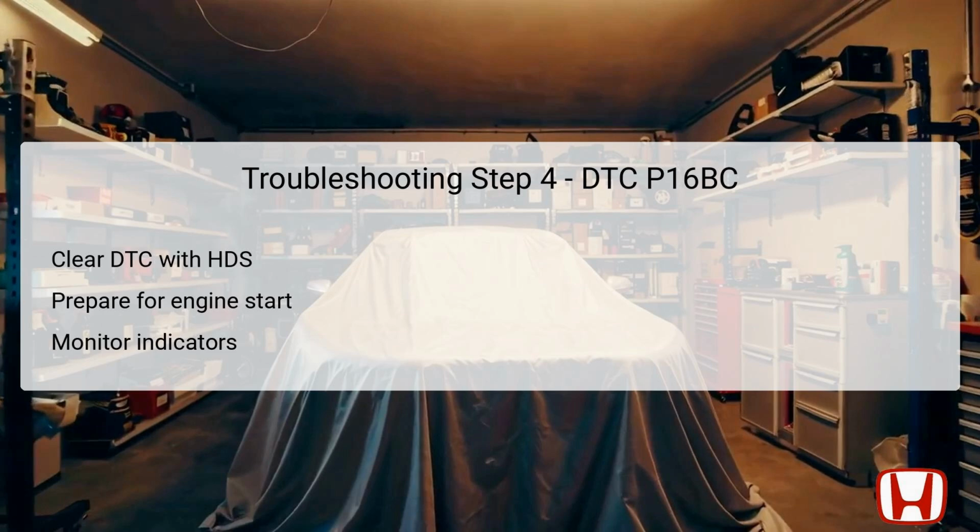After turning the ignition to the ON position, the next step is to clear the DTC using the HDS tool. This action resets the DTC status and allows for the next evaluation to take place under controlled conditions.